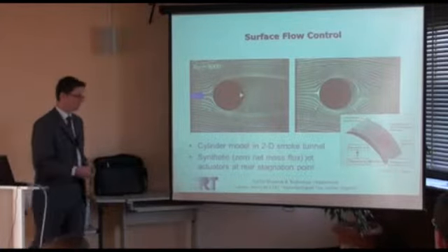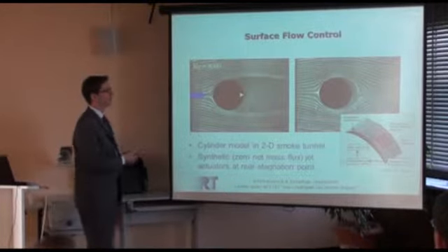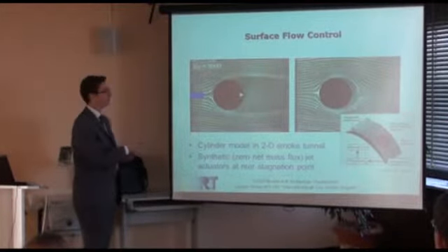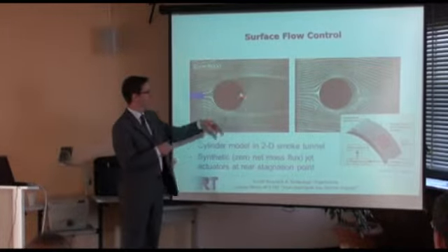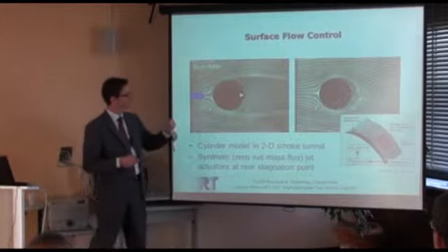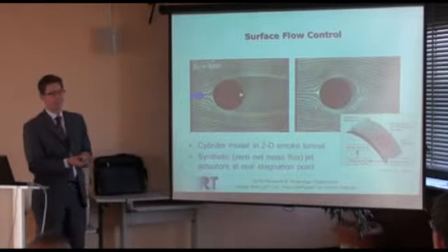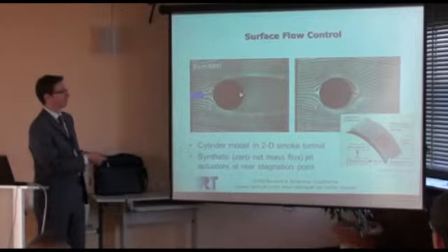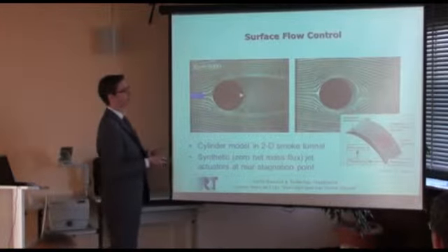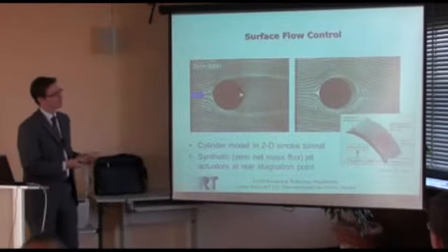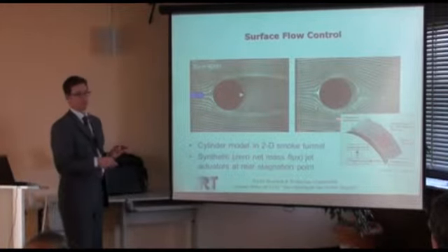Now what you can also do, instead of turning the boundary layer turbulent, is energize the boundary layer here in the wake. And that's done here by a jet at this yellow triangle position. There's a jet blowing out into the wake, which has been energized. And this makes the flow turn really around this ball, keeping a very low boundary layer.